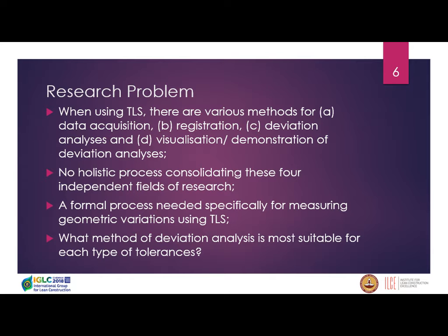What does it mean? You've got several scans, how you are going to put them next to each other, right? To get those 3D data sets from all your building or project. Then it's about how you are going to perform deviation analysis. So, for instance, how you are going to measure the flatness of concrete slabs, how you are going to measure the perpendicularity of columns.